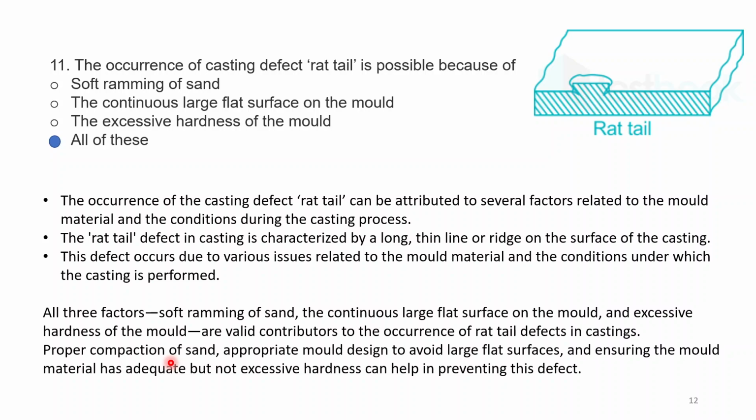Proper compaction of sand, appropriate mold design to avoid large flat surfaces, and ensuring the mold material has adequate but not excessive hardness can help in preventing this defect.